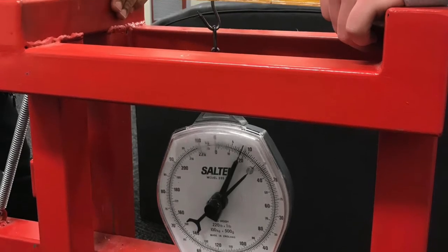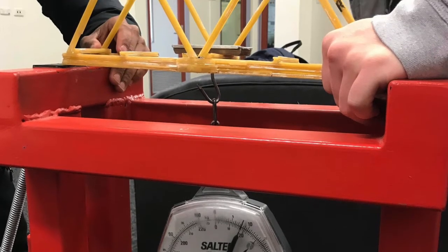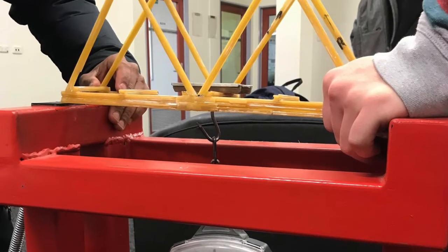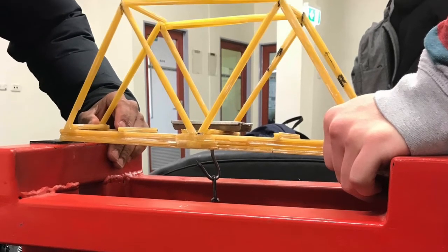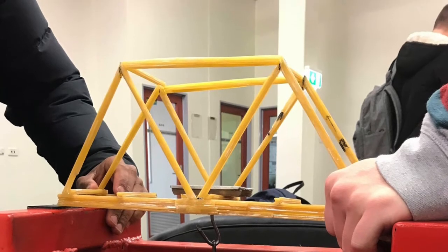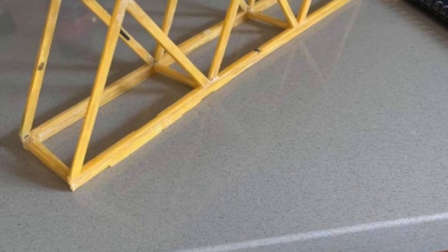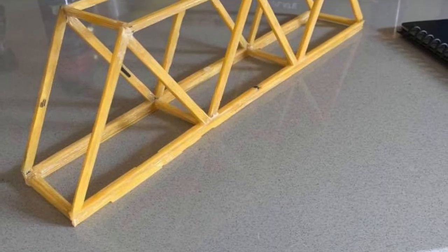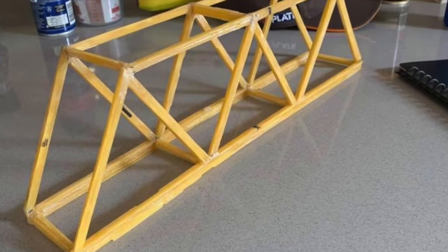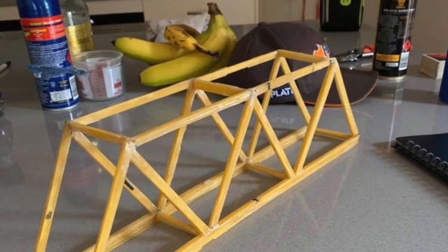In our first attempt, through our research, we decided to create 3 equilateral triangles with our truss bridge, but later through test results and more research, we decided that our first attempt was too small and the force of the weight wasn't focused on the middle of our bridge. So we extended our bridge and built 5 equilateral triangles, with a wider space in the middle of the bridge to place the weights, which we later learned was a wise choice as it held much more weight.